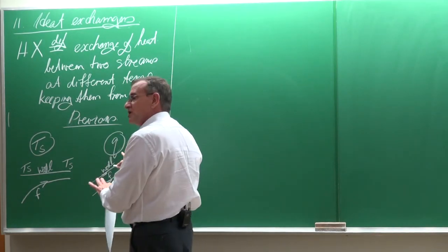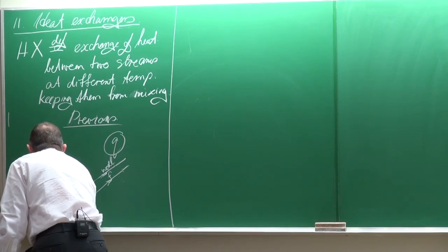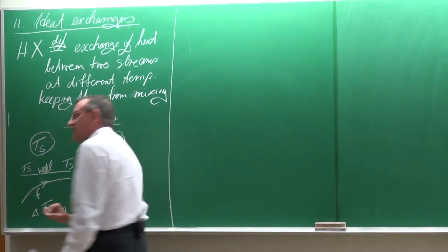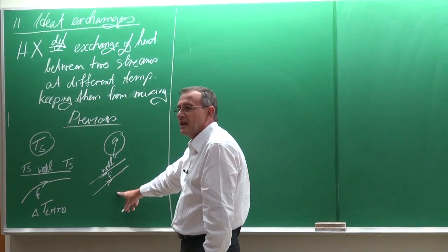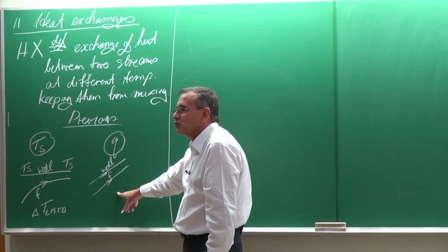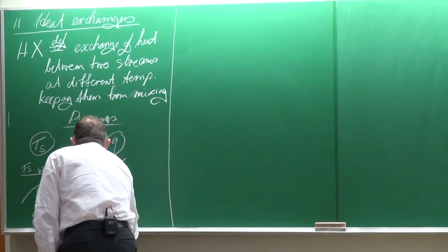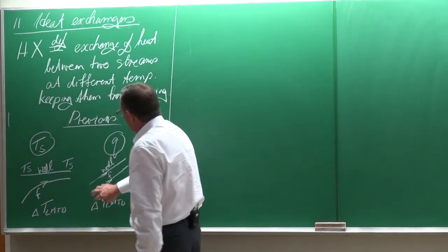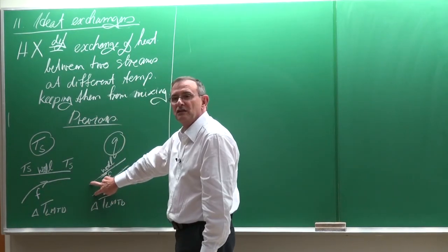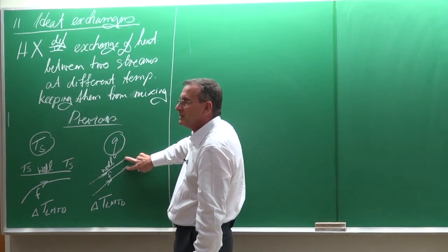With this, we've also seen that it is better to use the LMTD method. It is more accurate. And if you're going to try the LMTD here, you're going to see it doesn't work. So if you want to try and apply the LMTD, then you're going to get, maybe this temperature difference is 10, and then that temperature difference is also going to be 10.